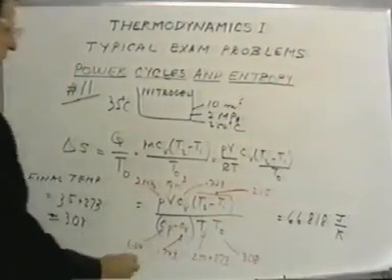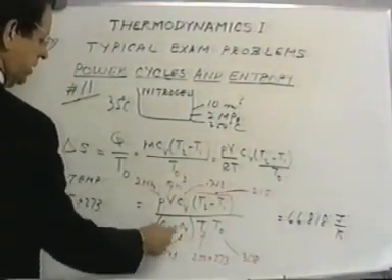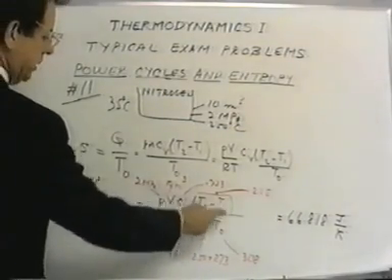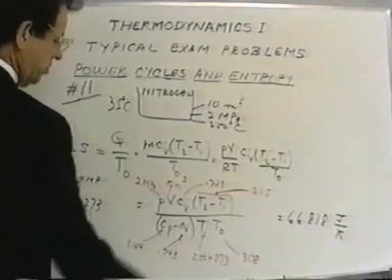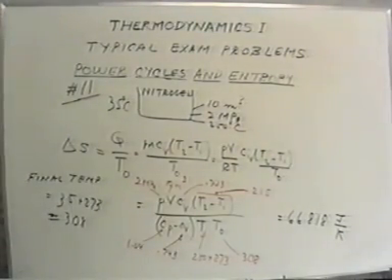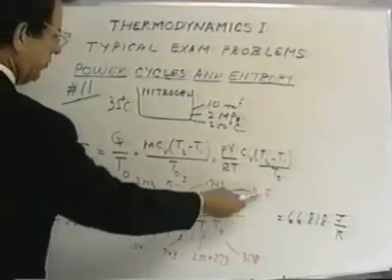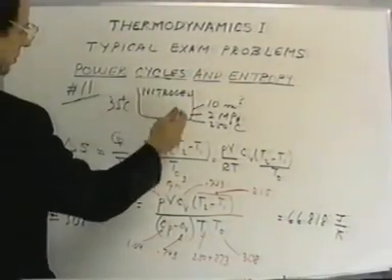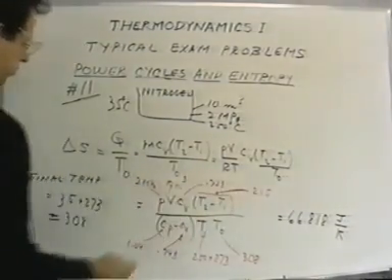Going down one line below this now, we can replace R by Cp minus Cv. And so we have P, V, C sub V, T2 minus T1, over Cp minus Cv, T sub 0. Well, the temperature difference we're dealing with here is 215 degrees between the surrounding temperature and the nitrogen. So this T2 minus T1 is 215.